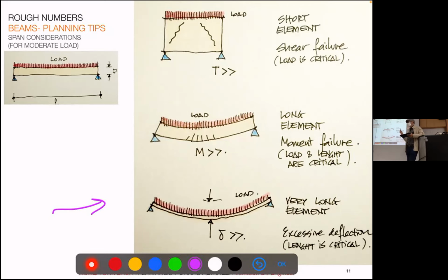So imagine we have over bending. Well, if the load stops, it will return to the beginning and will not have any problem. But if it rains, if it snows, that will put additional stress there, and it will bend even more, which will mean even more overload and eventually collapse, right? And when we say snow and rain, it can also be wind, right? So be careful with this, because it is not always the moment, as probably your mind has recorded from previous courses.